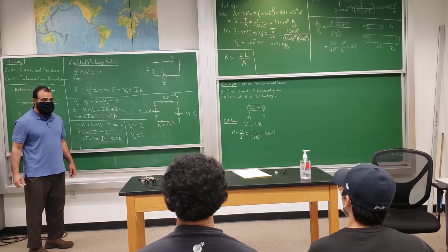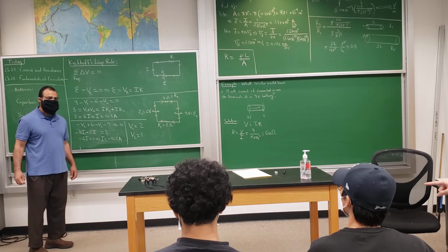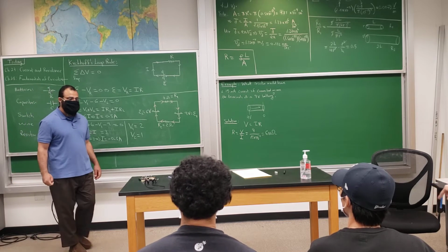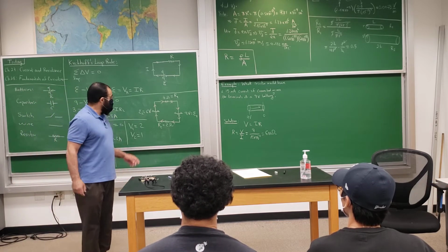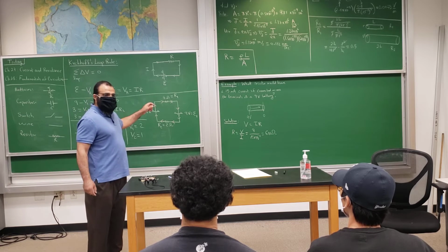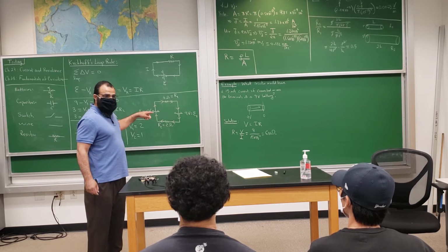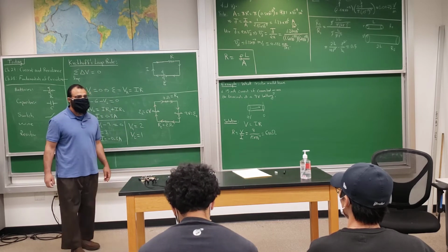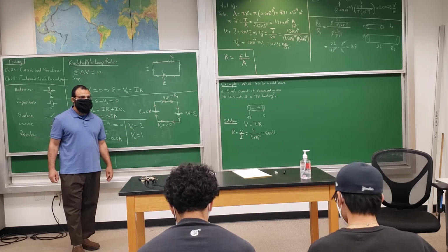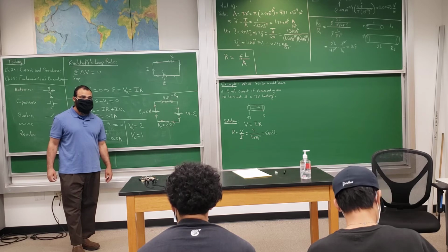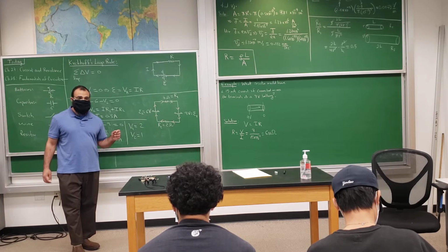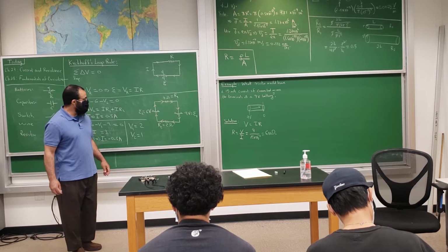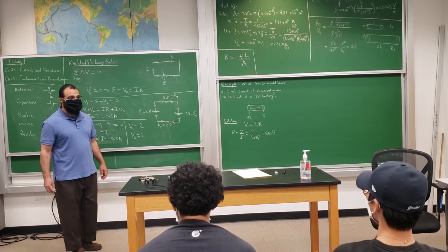These two resistors? Yeah. I was just messing around and thought, oh, there's an R1 plus R2. Yes, the definition of series is that if they have the same current, then they are in series. Even if there was a capacitor in between them, they'd still be in series. Unless there is a junction, yeah. If there is a junction, then it will be slightly different.